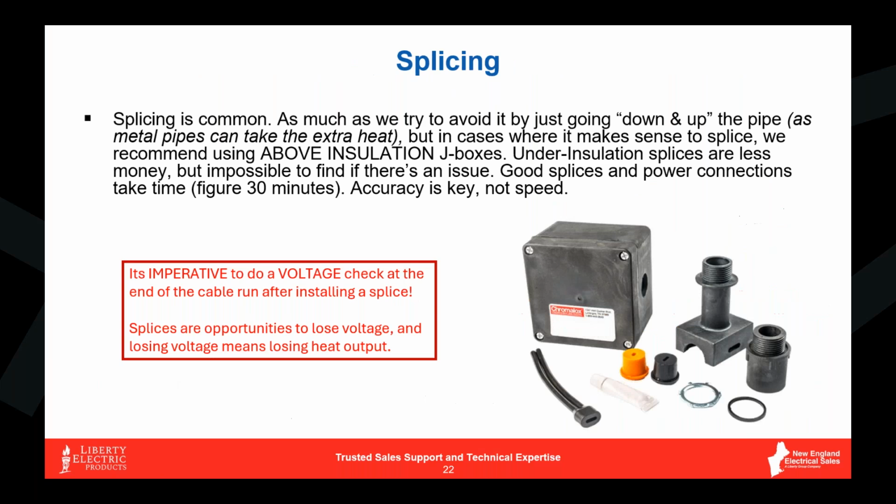All right, when we talk about splicing, really there's two things that heat cable does not like, and splicing is one of them and water is the second. Obviously splicing is a necessary thing. Splicing is the same thing as connecting power. So, I just made mention that it's half hour per termination, half hour for a splice.